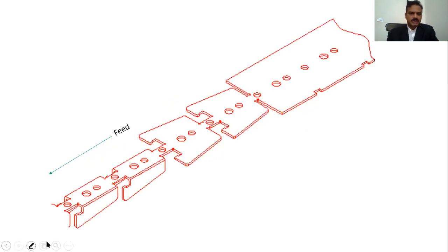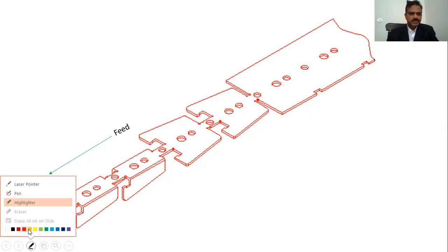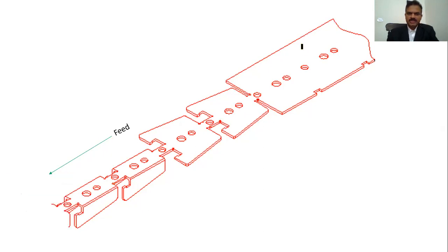So it's another isometric view of the thing. So you are feeding it in this direction. You see all the holes punched in the beginning and the notch, and here you do the cutting here, and make sure you are leaving some stock here, some material, some kind of meat, so that it can be shaved in a later stage. And in this position, you are going to bend it. So you're getting the U shape in here, and again feed it forward.